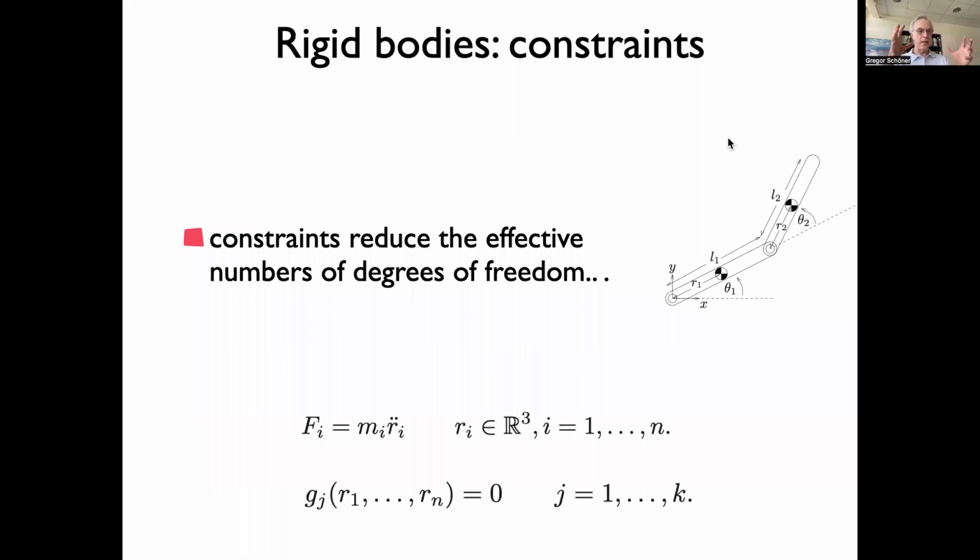So the 6 are the spatial position of the rigid body, x, y, z, and the orientation along 6 possible axes along which you could rotate these frames of reference, the rigid body. And so one rigid body has 6 degrees of freedom. So you fix 6 things to determine its configuration.